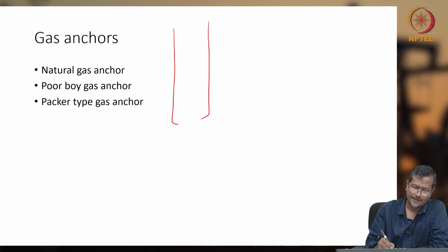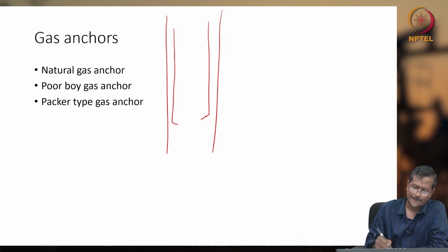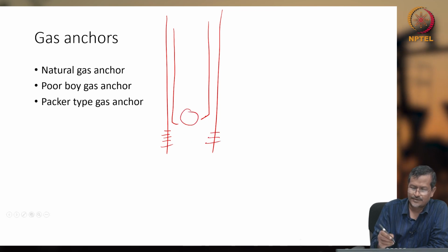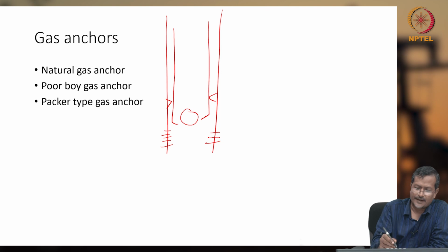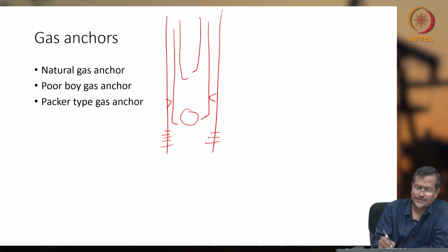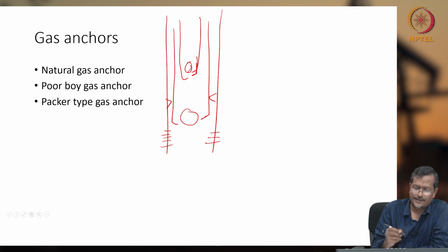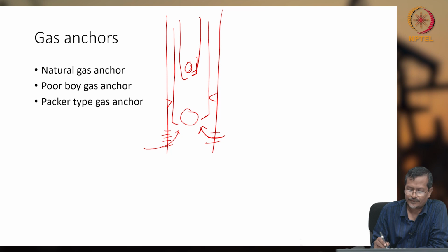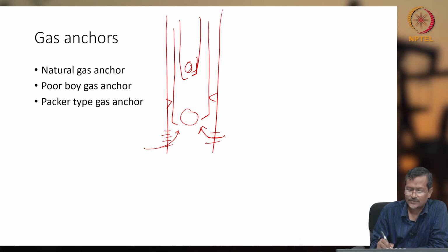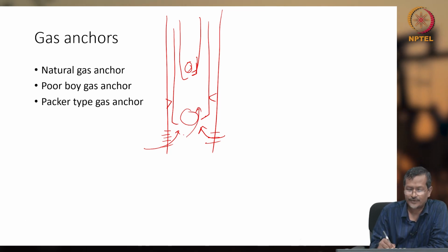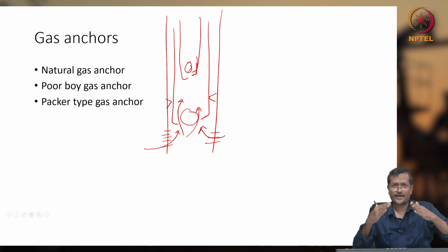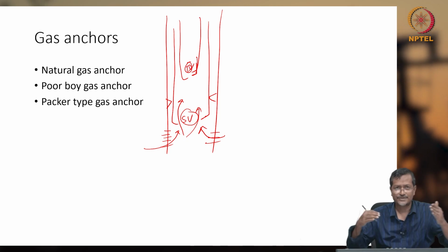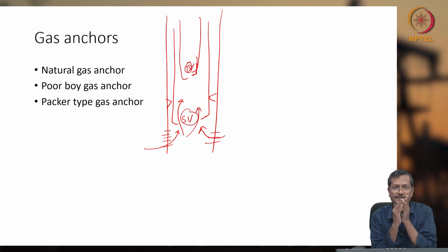One is that you have casing, and perforations are here, and your barrel is here, your plunger is here. Now what happens? Oil and gas will enter here, and if you have gas, gas also can enter here. So this will give you gas lock. If oil and gas enter, they will pass through the traveling valve, this is the standing valve, this is the TV, passing through the standing valve into that cavity, then you have a problem.